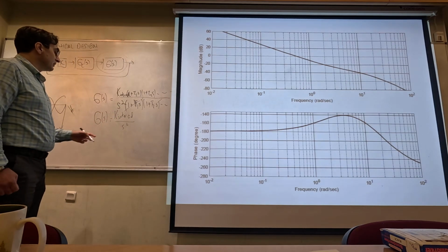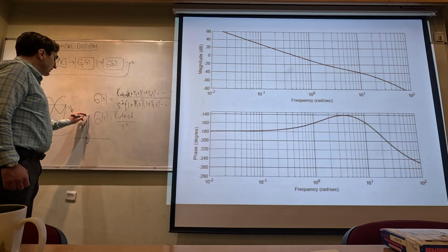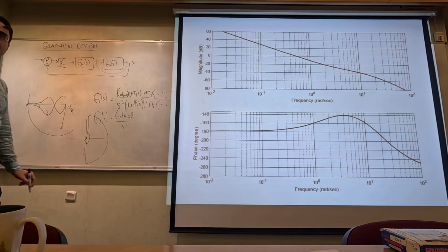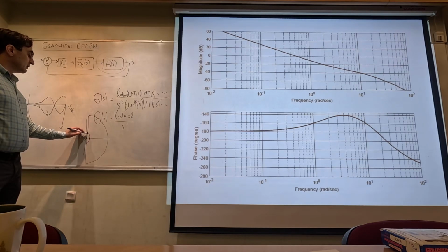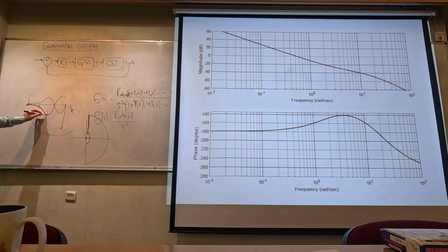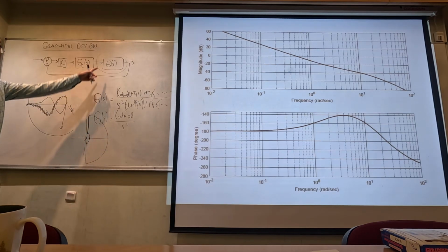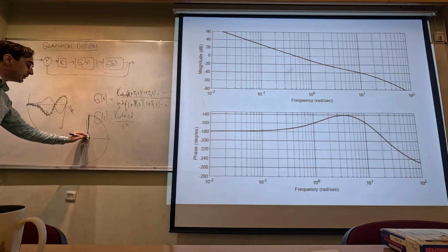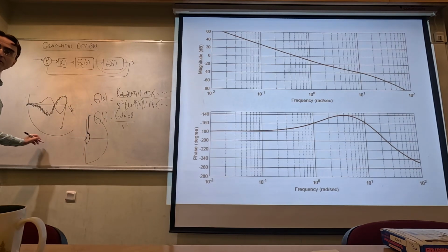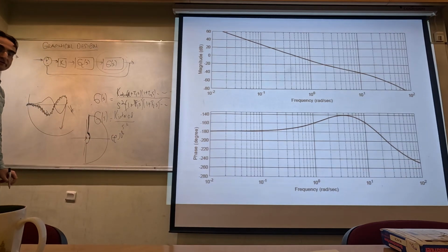And when I try to draw the Nyquist plot here, I'm going to come up with a Nyquist path, which is looking like this. This part here corresponds to the polar plot that I have drawn. This is the polar plot, okay? So this part of the Nyquist plot is the polar plot, and it's the frequency response of G of s, okay? But this part is going to be at infinity, okay? This part is epsilon e to the j theta, okay?